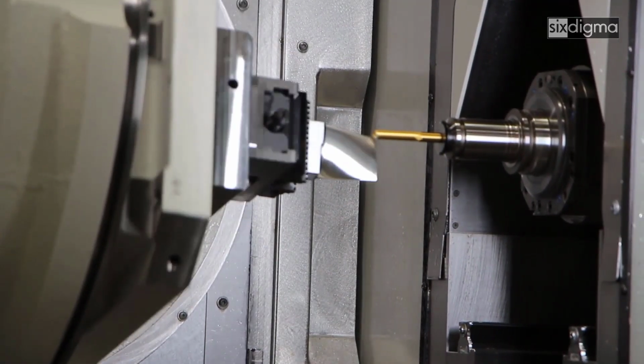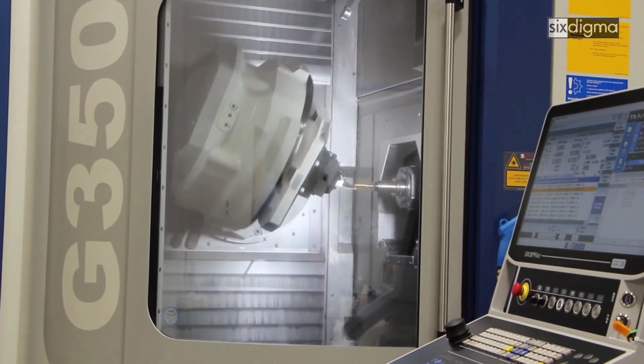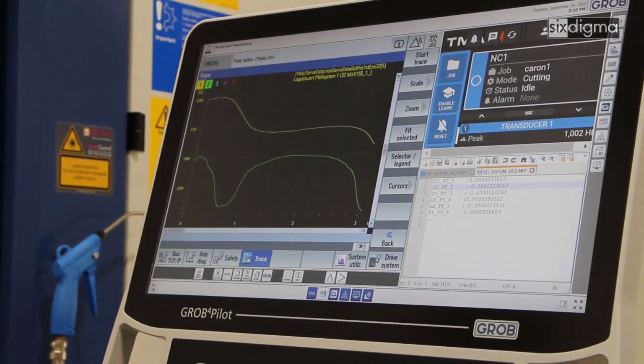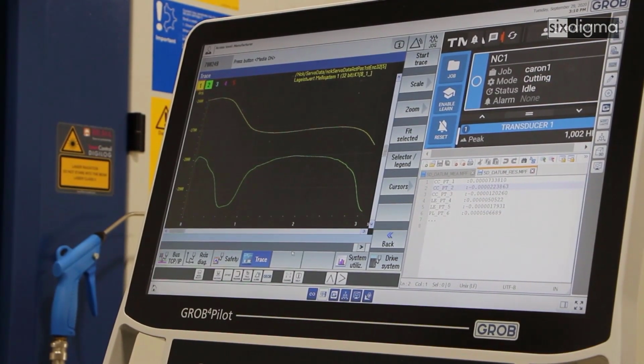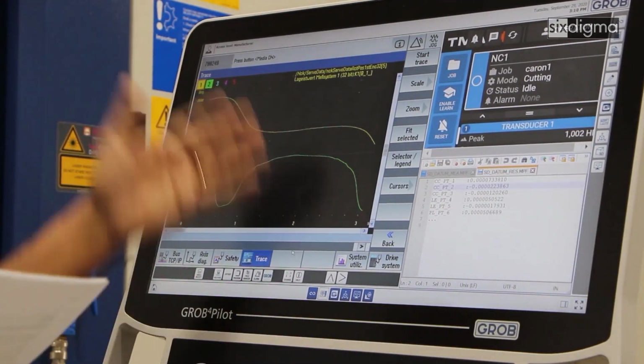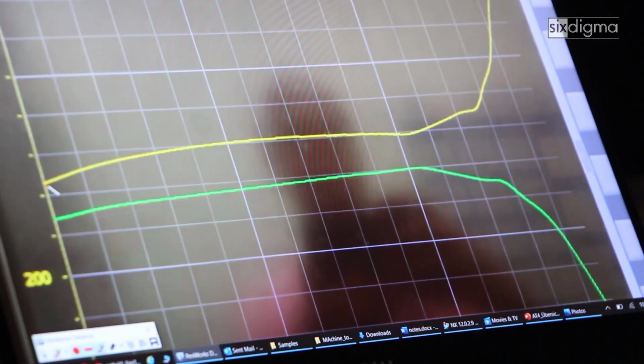There are instances, however, where these axis reversals are so hard to predict and identify. To circumvent this problem, Siemens provides onboard trace diagnostics for each axis, and we can monitor a variety of machine parameters using this trace function. In this example of the tool axis trace, the top curve shows the main rotary axis of the table.